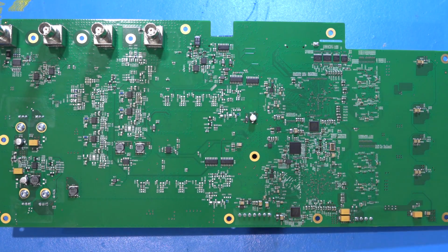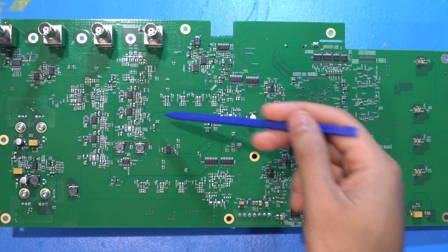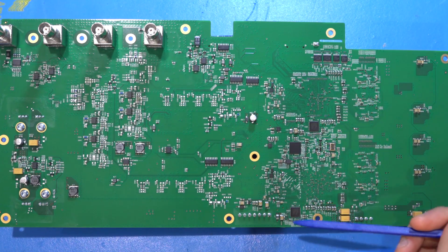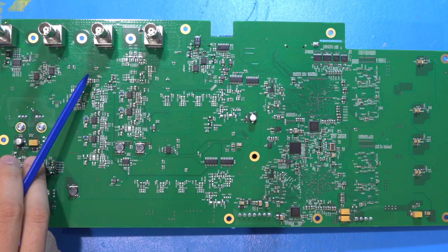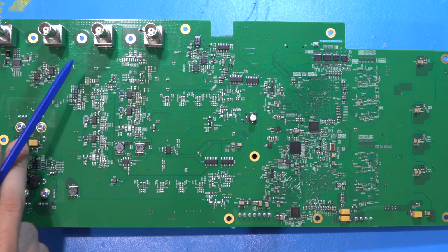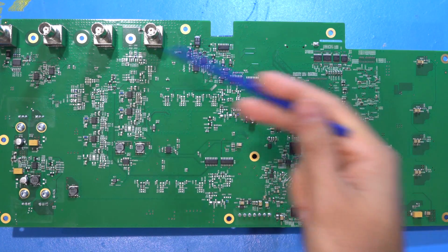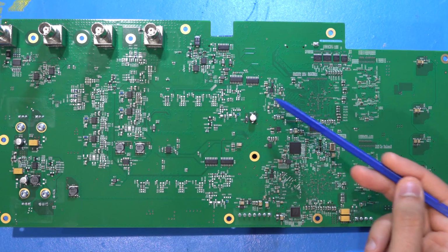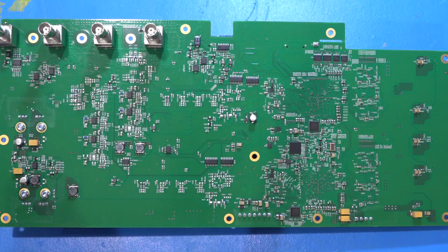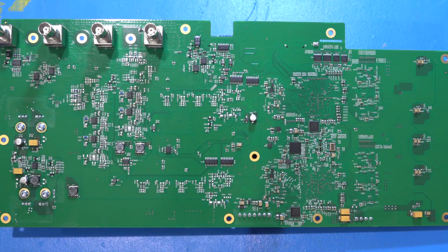You can either put the ADC really close to the output and have the digital lines go all over the place, or you can route the analog to the ADC and then have it close to the FPGAs and the SoC processor there, which kind of makes more sense, and that's what they've done here. And that's why I think that the conditioning IC is sitting very close to the output, and then the signals, once they're conditioned, boosted, and amplified, are sent back to the ADCs here, and that's how you close the InstaView loop. Remember that you cannot sample the output of the DAC. That's kind of useless. You have to sample the output right at the connector there, because that's where the impedance is going to make a difference. That's why it needs to go all the way back there.